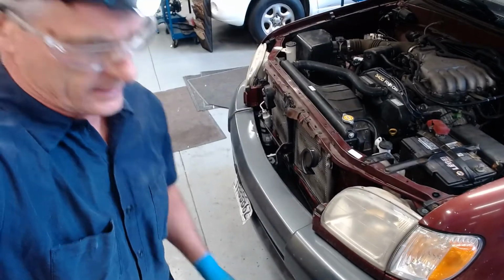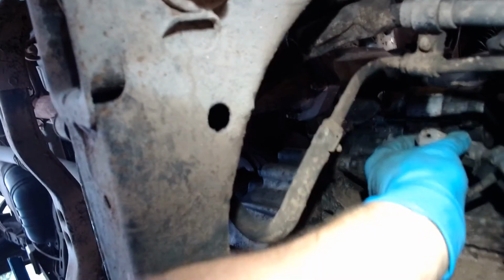So we've got a little flap here. So we'll put this up in the air, rock it, make sure it's safe. And then we'll take that tire off and see what the quickest way to get to that's going to be. Okay, we have this up in the air, and I think it's going to be much easier to take it out from the bottom here. There's the starter right there that clamps off. We've got to take this battery positive lead off, which is a 12 millimeter, and then we unplug that guy there. And I'll do that right now.